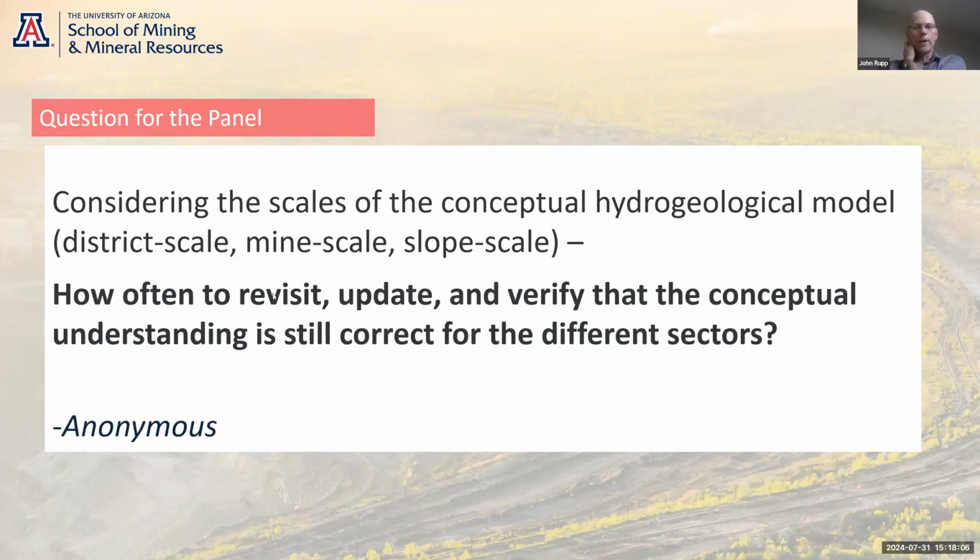I was going to say that in operations, there are typically natural breaks that are tied to slope redesign or instability. So if you have a new instability come online, you might get some new information that will change your slope scale understanding. The mine scale often naturally gets a new batch of information related to a pushback. The district scale is usually established during feasibility, and then not updated quite as frequently. But if there's any major event or data gathering that happens, then that's a natural time to update.